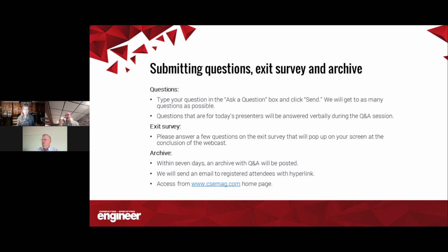And another question I commonly get is, how do I provide annunciation to this temporary generator? Those are questions you have to have with your AHJ regarding how much time you're going to be using the temporary generator, how it's going to be monitored, what the type of facility it is. Are you doing it when it's occupied or unoccupied? All of that could factor in. But we want to make sure that it's a backup to our permanent installation, and it isn't exempt from the starting times that our permanent installation has to have.